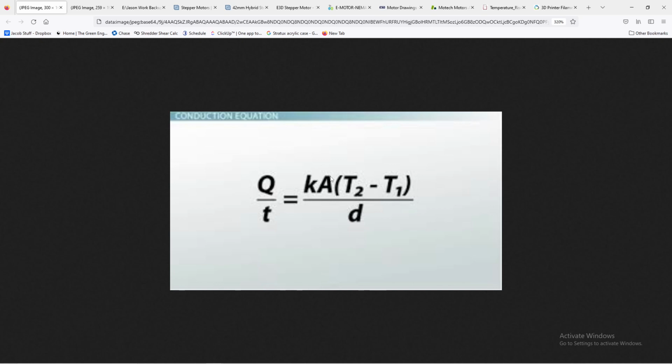Either they have the settings set up on the stepper driver that allow it to use less power, maybe like a silent mode or something like that, or they are using high temperature tolerant steppers, right? One of those two things, or possibly a combination of those two things, right?